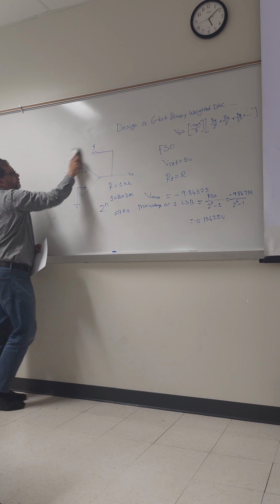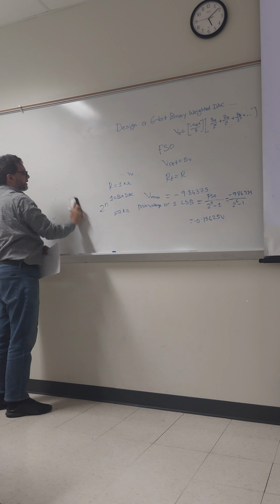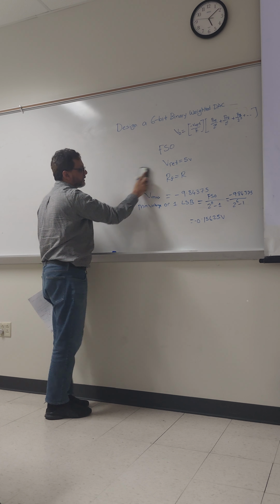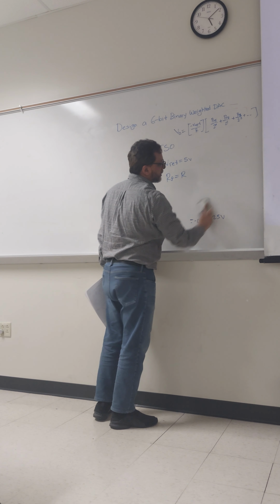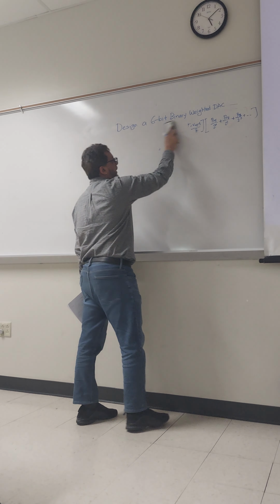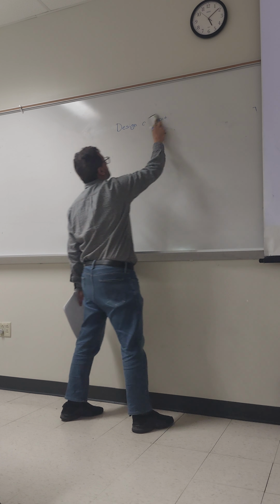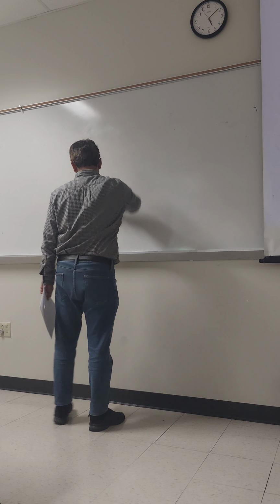So it is not always possible to have the exact value of the resistance, right? If we can reduce the variation of the resistors, it will be better. This is the technique where we can get the design using only 2 different kinds of resistors. That's why it is known as the R2R ladder circuit.